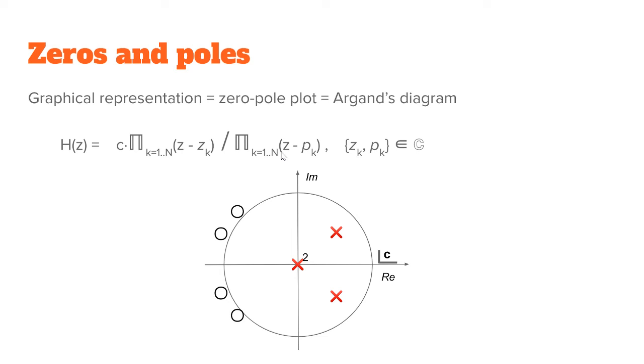But currently, you need to know practically that if we have these zeros and poles of the system, the poles would usually be inside the unit circle, because outside is unstable to put the poles.